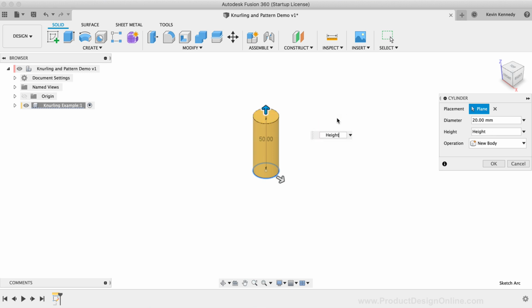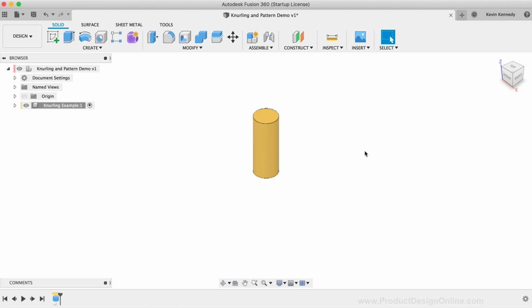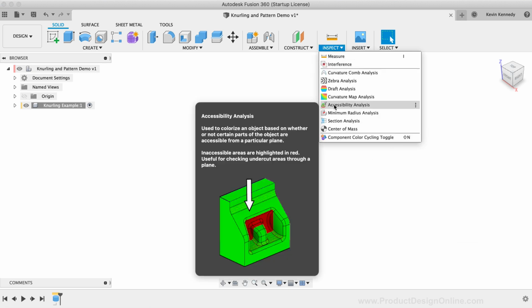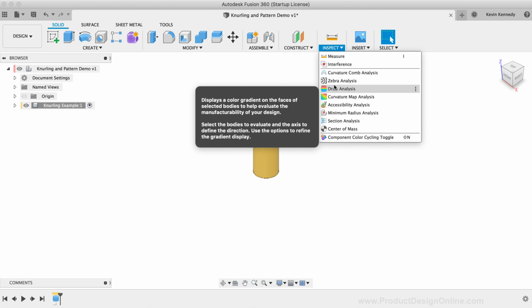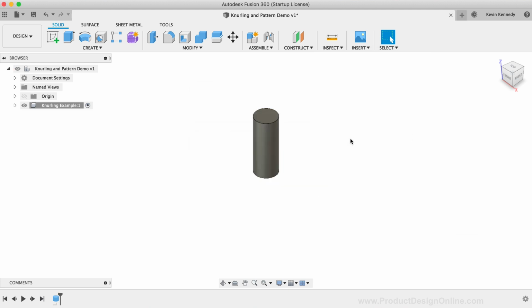There are a couple of different common patterns for knurled surfaces. For this first demo, I'll show you how to make a very simple knurled pattern, which can then be altered based on the number of instances. To do this, we'll need to simply cut out a shape that follows a coiled path, and then we'll repeat these steps in the opposite direction.